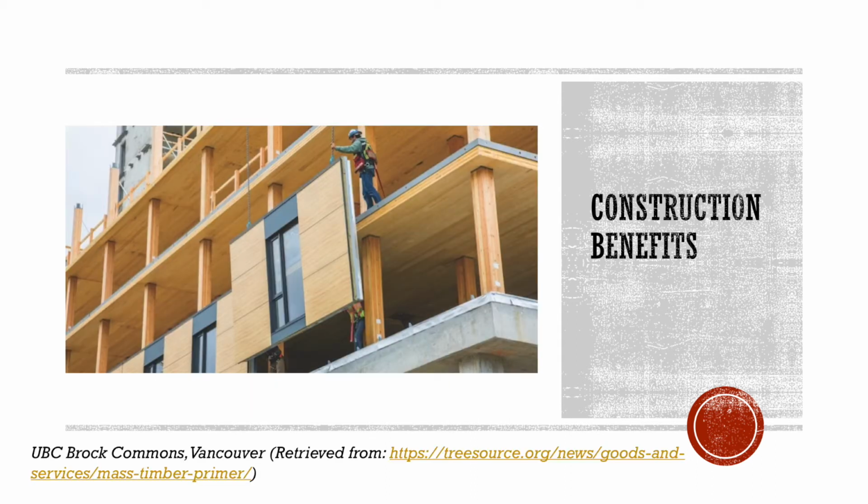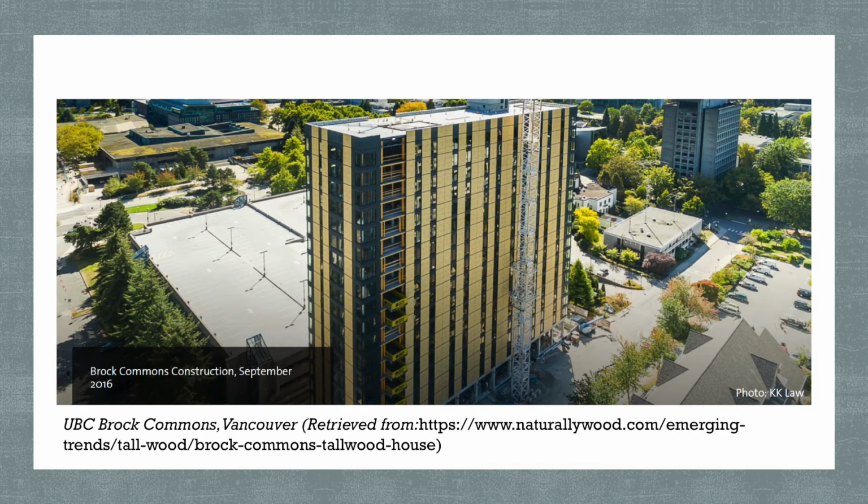Since the panels are manufactured in a climate-controlled factory environment, consistency is improved, and this creates fewer quality-related reworks on site. CLT panels are often sequenced to arrive on site as a kit, in order and as required, saving precious site storage space in dense urban environments. The construction benefits of CLT lead to more cost-effective construction, aesthetically pleasing structures, and a reduced environmental impact.